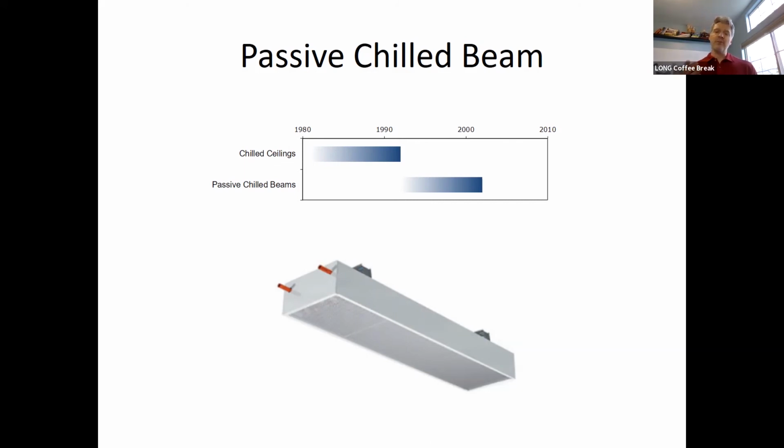So in the ceiling, radiant panels do a pretty good job. We put insulation behind them to try and drive heat transfer into the space itself. So there's not a lot of chance for convective to happen in that space. There will be some that happens though, and those have a pretty high radiant percentage of their heating value.